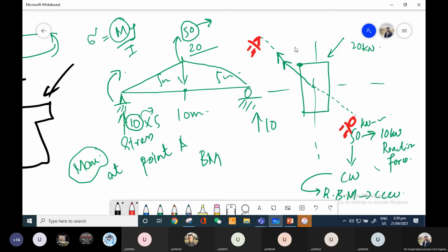Since the load is acting inclined to this particular beam, I can say that this beam is something like this one, and you have to show this moment arrow on the same side at which the load is acting. For example, over here, the load is acting towards the left side, so you have to show these double-headed arrows towards the left side. This is the left side of the beam, and this is the right side, right?